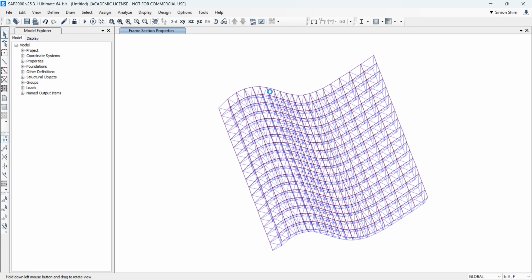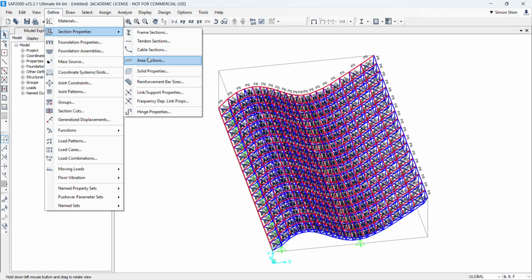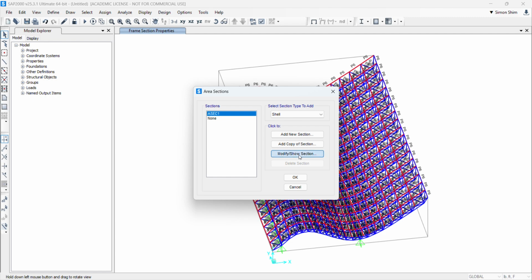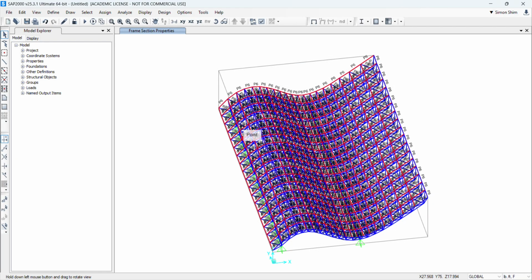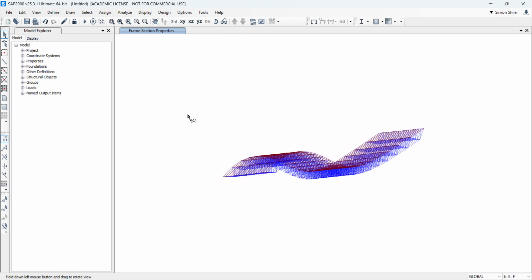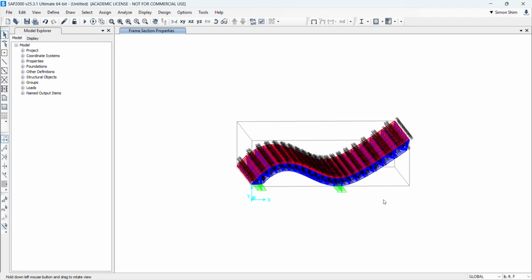And the slab, we have one default, right? I just said the default is 1 foot, which is not going to be a concrete slab. This is most likely a metal deck, so I assume it's going to be just 1 inch. So I convert it to 1 inch, right? Even 1 inch is a lot, but it's a deck or plate. And then I'm going to choose steel instead of concrete, right? So basically, we complete the geometry we brought.